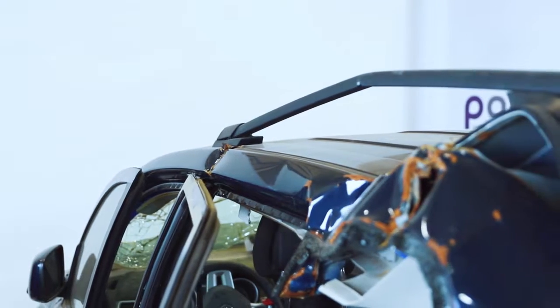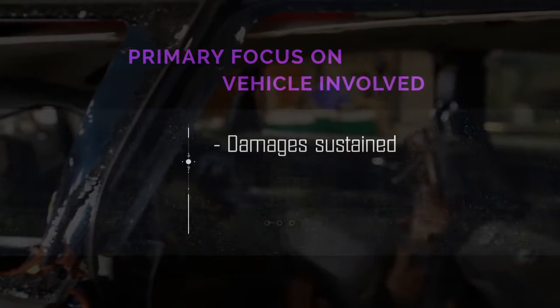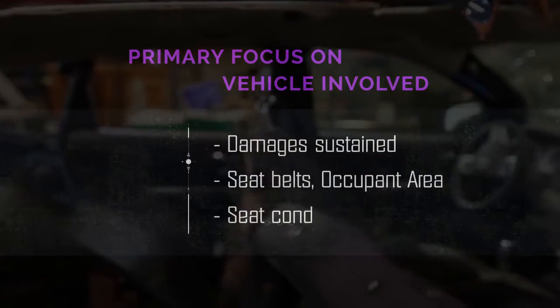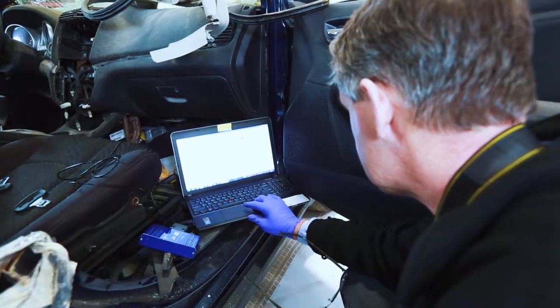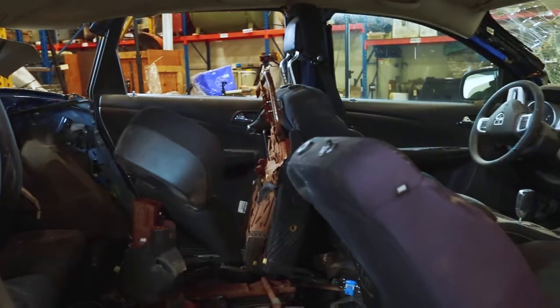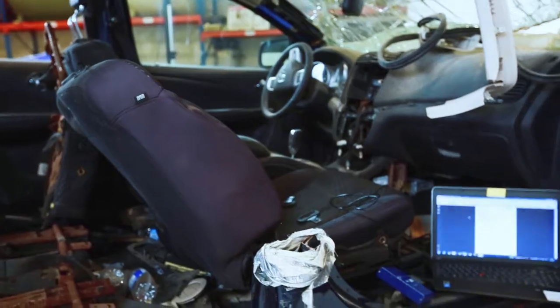As far as the vehicle inspection is concerned, we're focused primarily on what damage the vehicle has sustained. Also look at the interior as far as the basics, as far as seatbelts, occupant impact damage, the condition of the seats. And also we have the capability of downloading the crash data from the majority of the vehicles, and also to be able to download if there are any data trouble codes, we do that as well. And then from that, we'll be able to use in our 3D computer crash simulations.